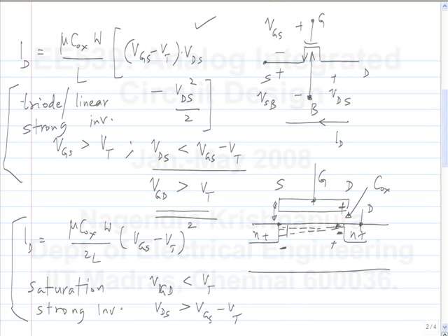It gets pinched off here, and as you increase the drain voltage, the depletion width increases in this region. It pushes the pinch off point closer to the source. So, effectively, it's like the length of the channel has reduced. The same voltage drops across a smaller length, so that means a higher field and a greater current. So the same equation holds if you make L dependent on VDS.